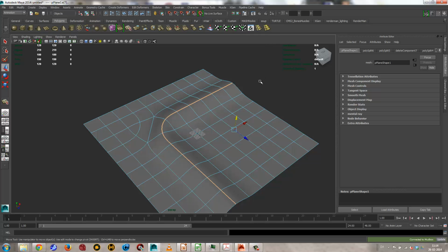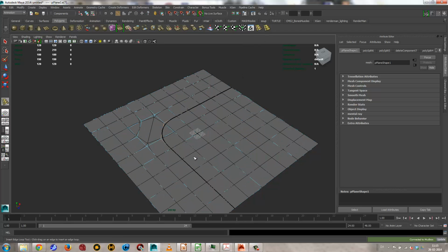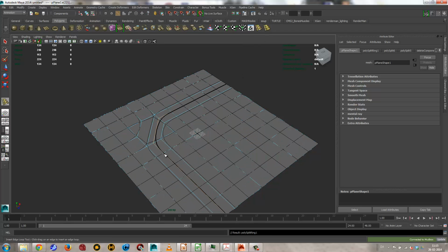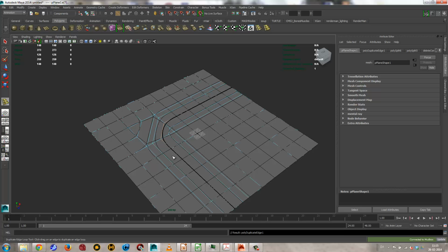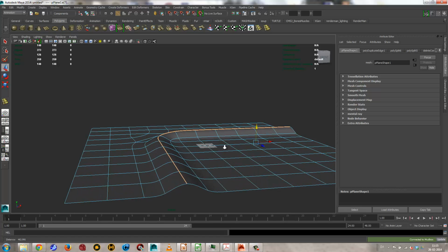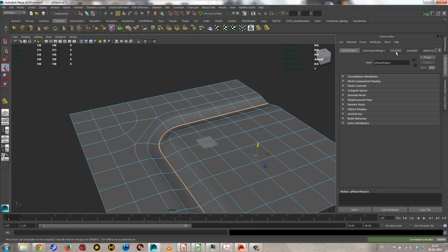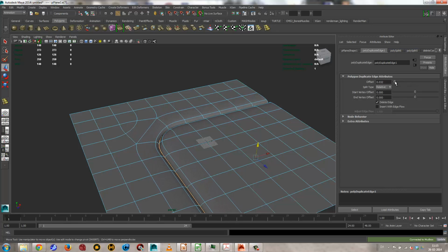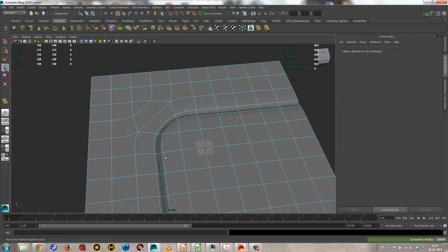There's also this thing called offset edge loop. So like I can insert an edge loop, like so. There's another option called offset where I click on the actual loop and I add one to both sides. So something like this, and then I can drag this up later because now I've added, maybe drag this down, and then I can go to my edge loop here and tighten it up so I can get nice looking sharp edges.